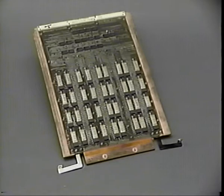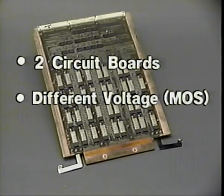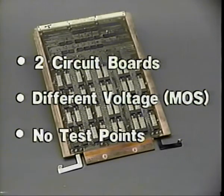XMP memory modules are similar to logic modules with 3 basic differences. Memory modules are made up of only 2 circuit boards. These boards are mounted on a single cold plate and are labeled A and M. The second difference is that MOS memory chips require different operating voltages than the logic gate arrays. And finally, memory modules do not have any test points.